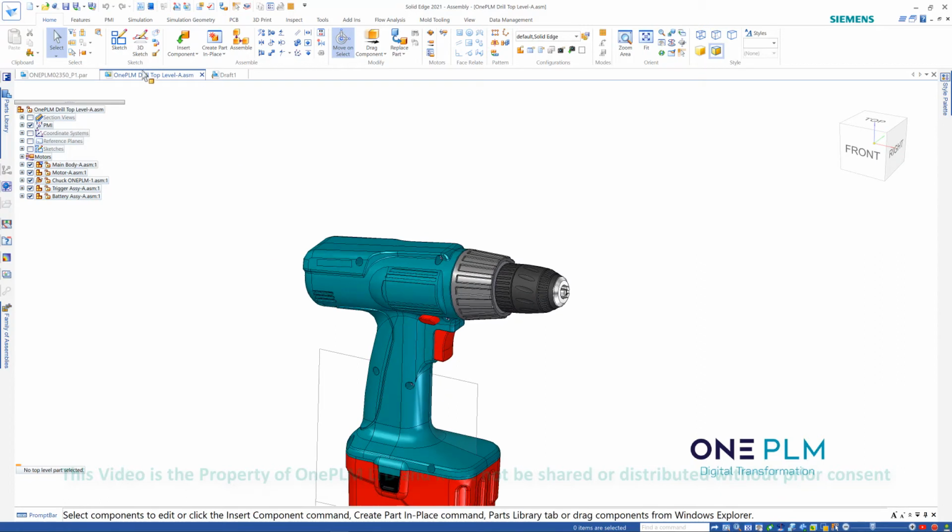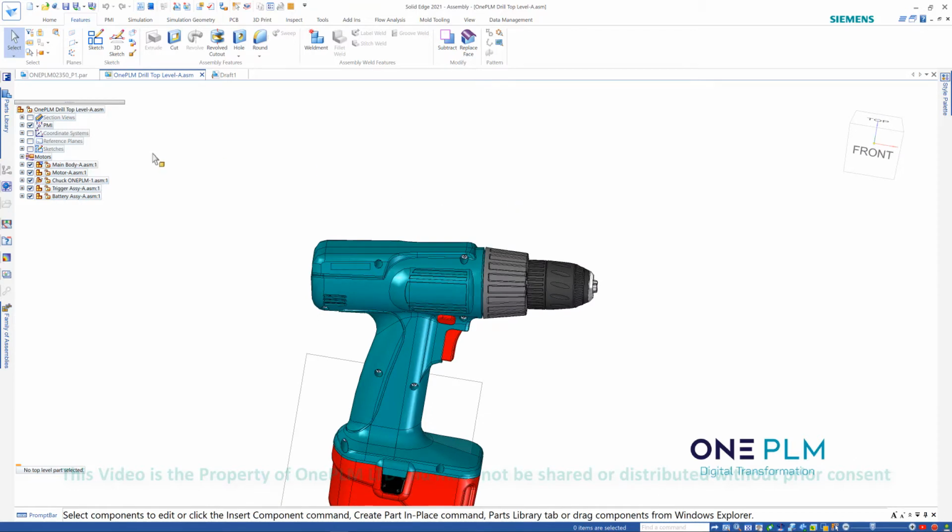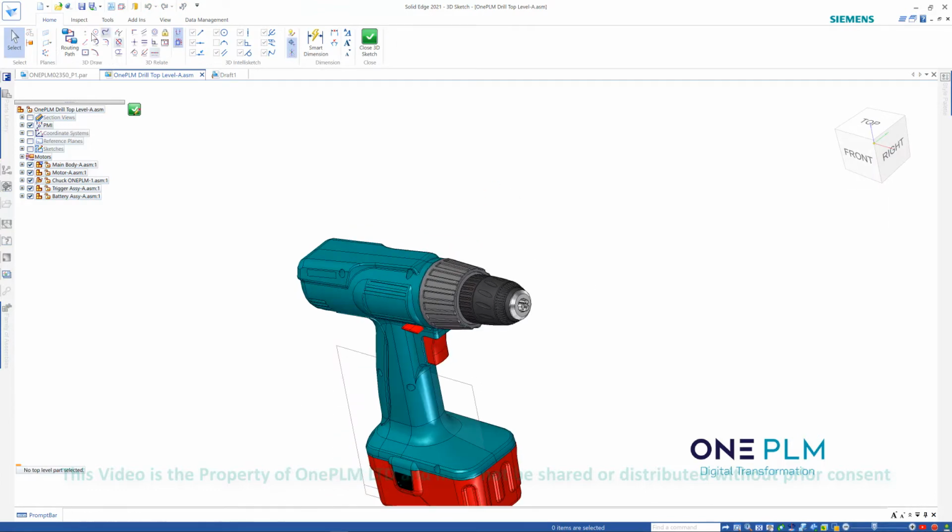For the plane commands option, because I'm in assembly, I don't have to do this option. But these options where we can do a parallel, angle, normal to curve, but we haven't actually got a curve on there. We can create a curve several different ways. What I'm going to do is use a 3D sketch to create the appropriate kind of curve that I want on there.